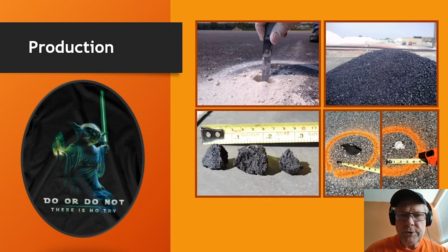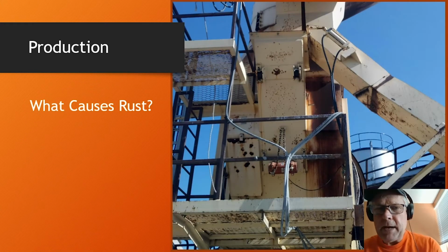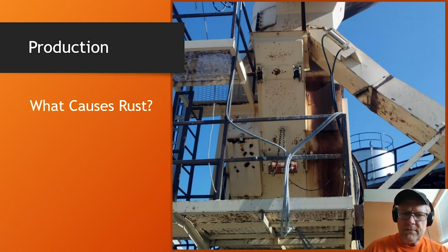So in production, you have to pay attention to the output from your input. Make sure the drum's warm enough. Make sure it's maintained properly. Heat and dry your aggregates adequately to make sure that you don't have dust balls. Watch out for debris, things like that. And we talked about segregation. If you see the back end of a drum, the flame is coming towards us. In this particular case, the ductwork takes out the elevated temperature, the steam, and emissions and whatnot.